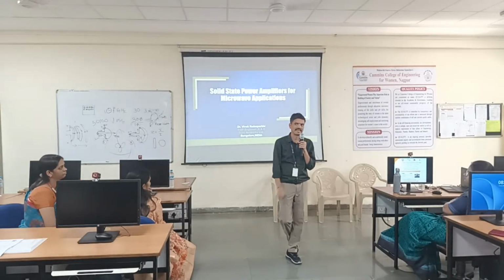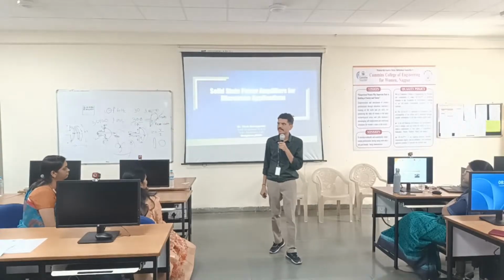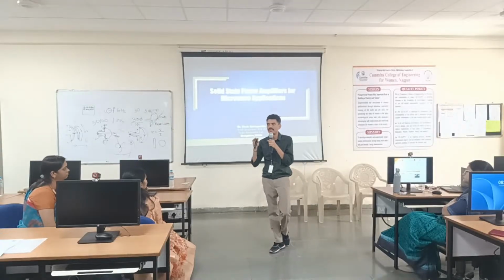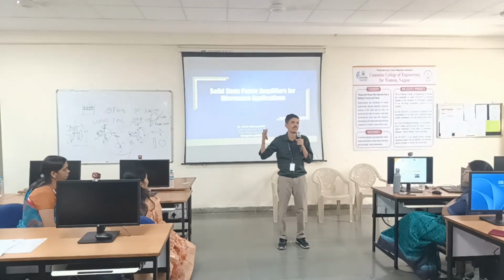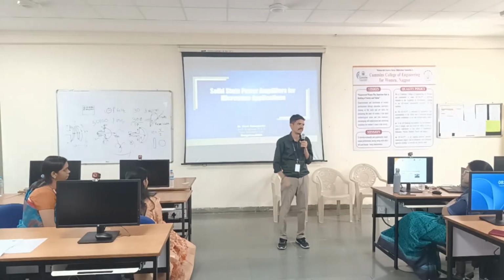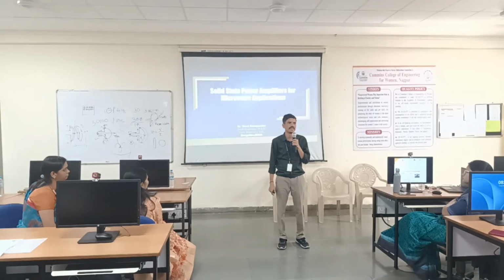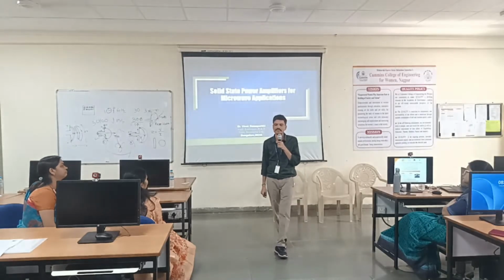What is the problem with that? If you have to design a traveling wave tube amplifier, the first thing is it is very large, and its weight would be more. So if you don't have any weight constraint, then you can go ahead with the TWT. Where do you have weight constraints?